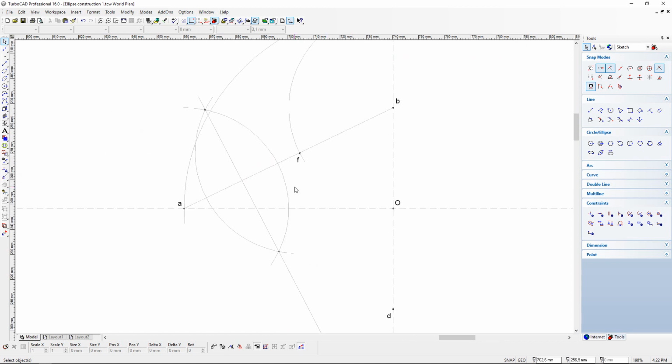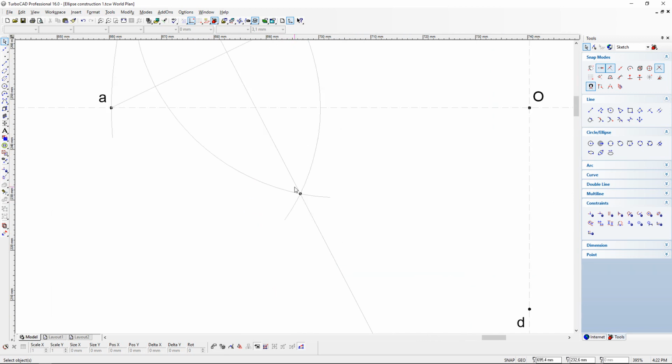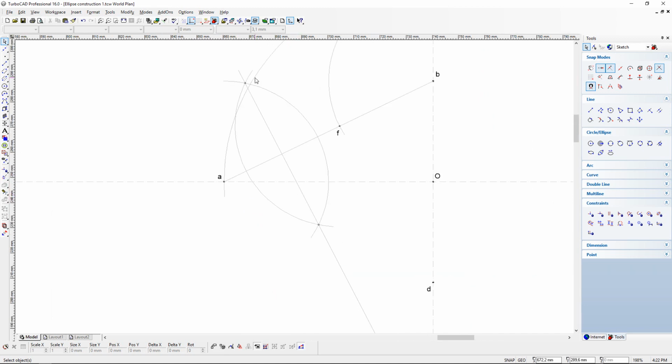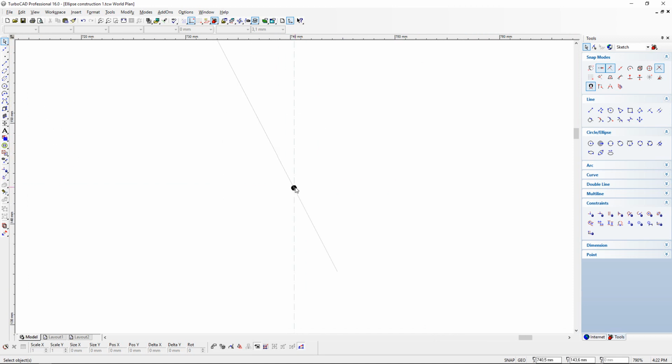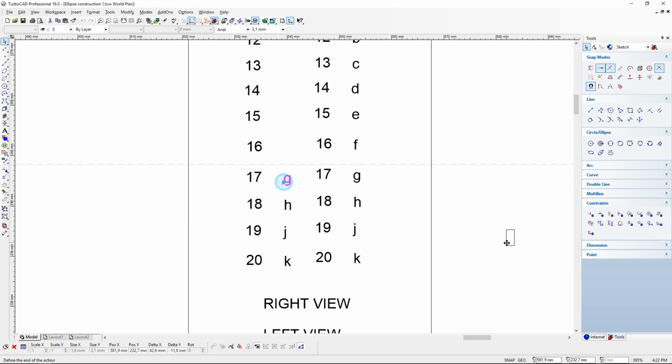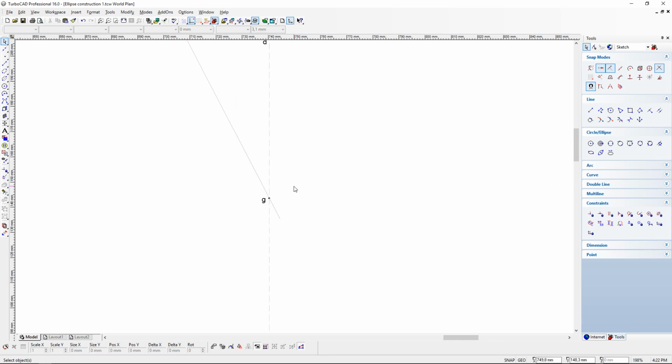Now what I have to see is which label I should call it. Well, I only label the defined points that I'm going to use as part of the steps for completing my ellipse. Therefore, I am not going to label these two dots over here that I used to determine this half of line AF, but I want to have this dot at the bottom, and I want to define it now as G, because that's the next letter that I need for my construction, and I'm going to place G here at the bottom.